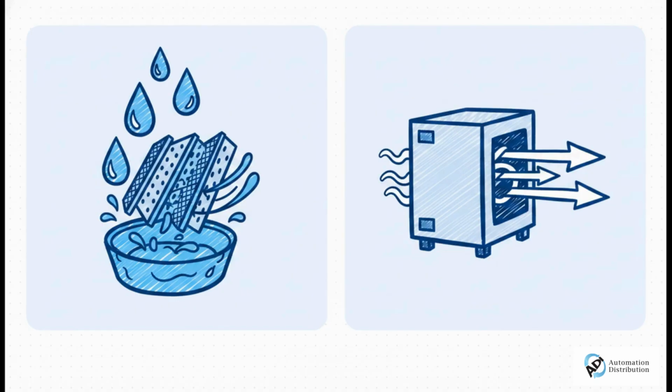And this brilliantly illustrates a vital distinction you have to make when you do that audit. Water separators address liquid water. They mechanically remove droplets using physical force or filters, but they do not fix water vapor. If your facility needs to remove invisible water vapor to guarantee that condensation doesn't just reform later down the line, you have to reduce the dew point of the air. And to do that, you need an air dryer, either refrigerated or desiccant. It's pretty simple. Separators are for liquid, dryers are for vapor.